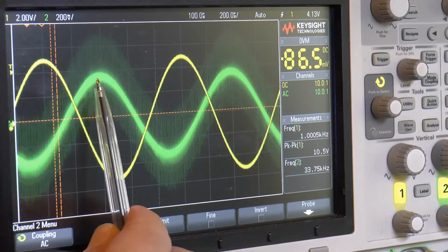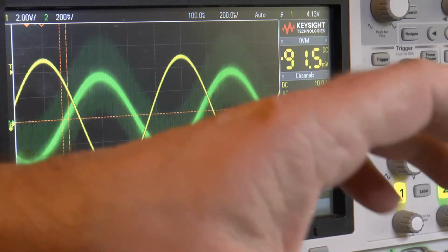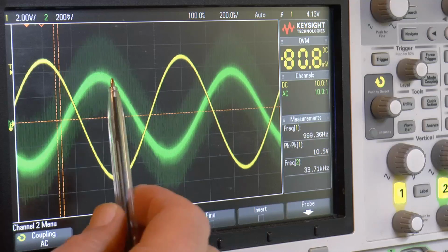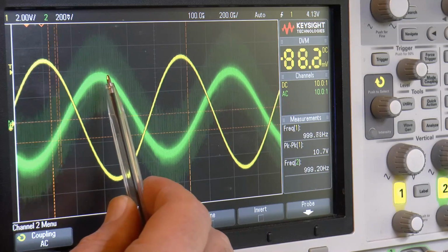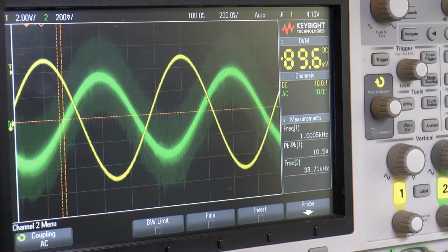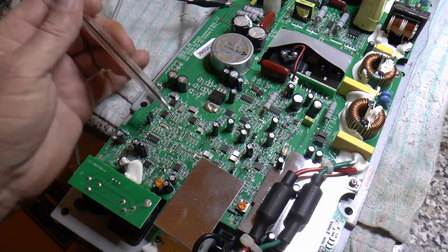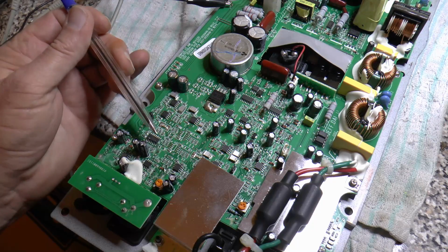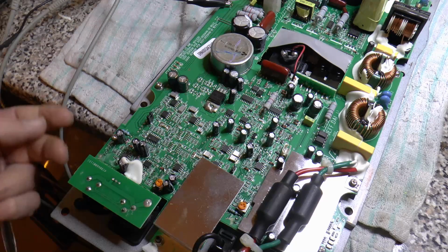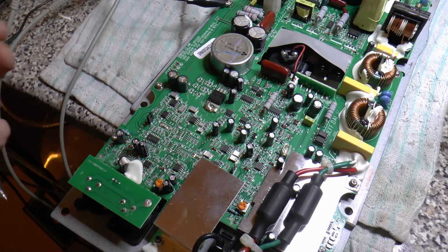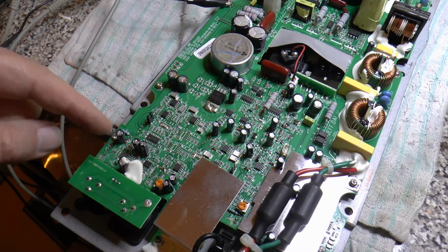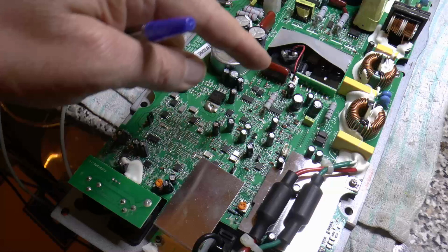Now, if the treble's 180 degrees out of phase, I guess you swap the wires on the horn and bring it back into phase. But it's not totally 180 degrees out of phase. So I'm guessing in the early days someone wanted the treble in phase with the bass, because this bass has got various filters for the low frequency and it's got band amplification and bottom end amplification, sort of 60 to 120 hertz, the bass goes through more chips than the treble.